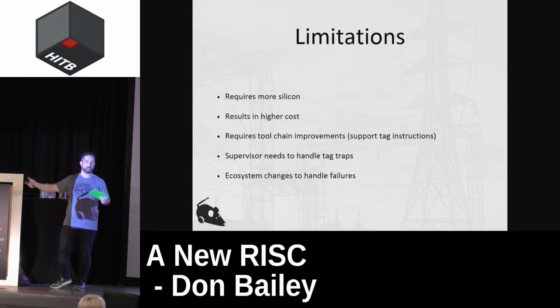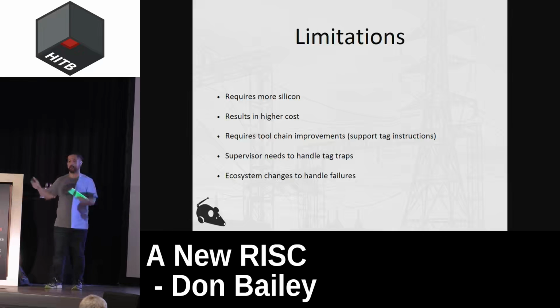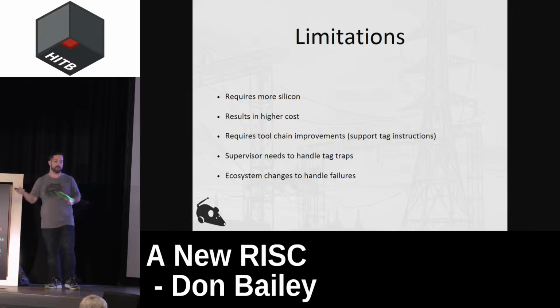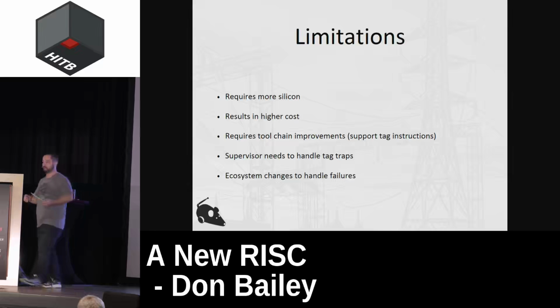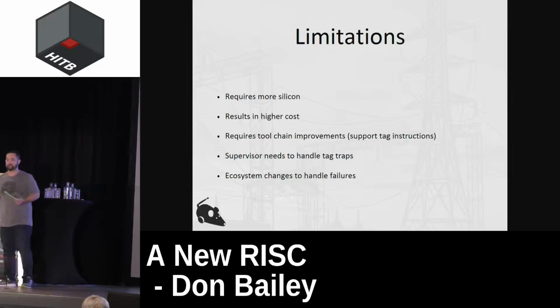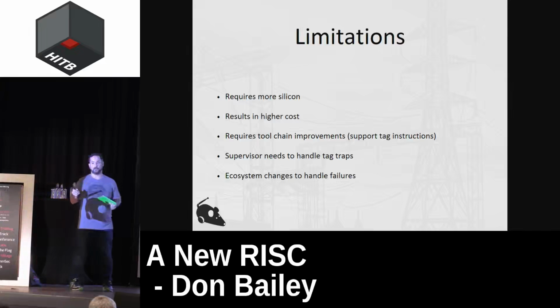For every single address line that goes into the TLB, it also has to have associated metadata. So now you have to manage the metadata as well as the address lines in every part of the MMU, TLB, et cetera. Every CPU or object has to be aware of this type of tagging technology, which is why you really rarely see this technology implemented, right? Because the costs skyrocket. And it's not just silicon, it's actually the ecosystem involved in developing technology as well.